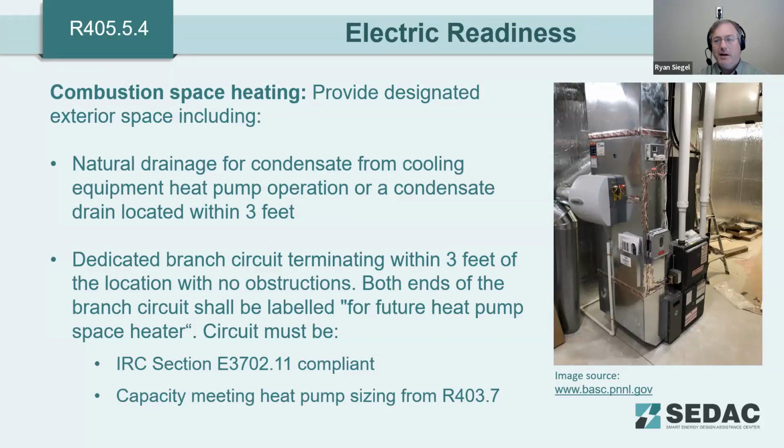This is where we have encountered facilities where they start to look at this and say, oh, in order to make this transition, I'm going to have to move from a 100 amp service to an 800 amp service. Something tells us that the sizing was not done properly for that.